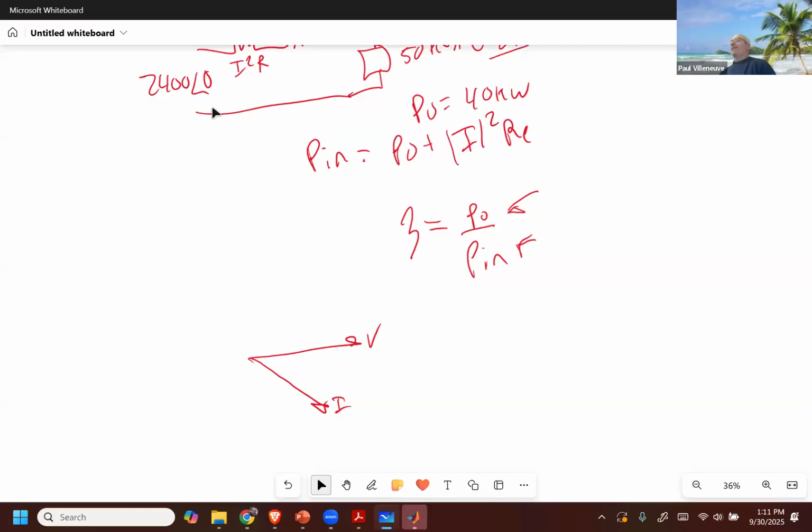What about the power diagram? Don't want the power diagram either. Phasors are really important to us because when we start looking at power flows, we really will need to understand magnitudes and angles. And getting those relative terms is really, really helpful for us to understand and troubleshoot things.